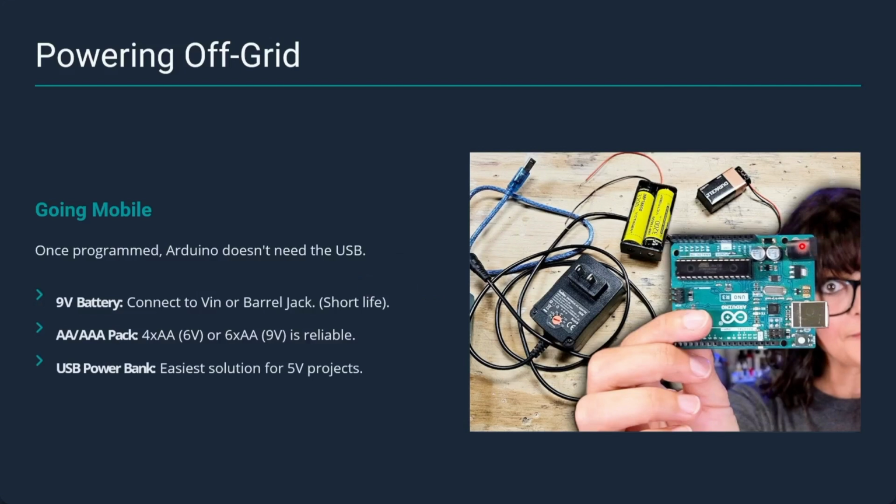You can give power using a 9-volt battery. We can give it to this barrel jack, or you can also give it here at the Vin pin. The power will come to all. Another thing, if you give power here and take Vin and give it somewhere, it will take the direct power, however much is coming. Suppose 12 volts is coming here. If you have connected a sensor to Vin, then that sensor will burn, because however many volts come here, that much comes at Vin. So don't connect anything there. We should use only the 5 volt and 3 volt pins.